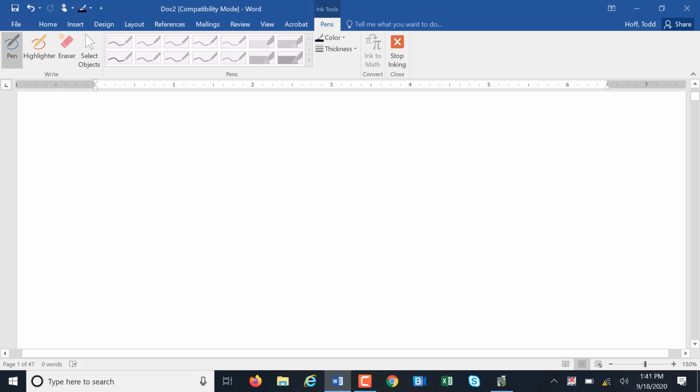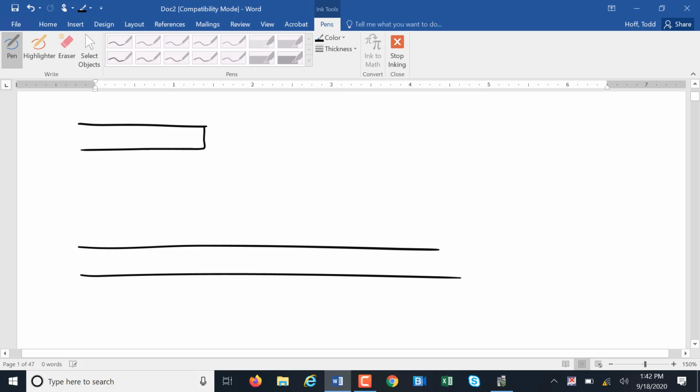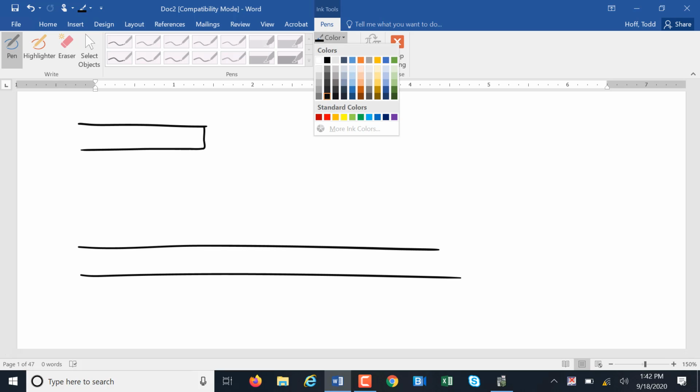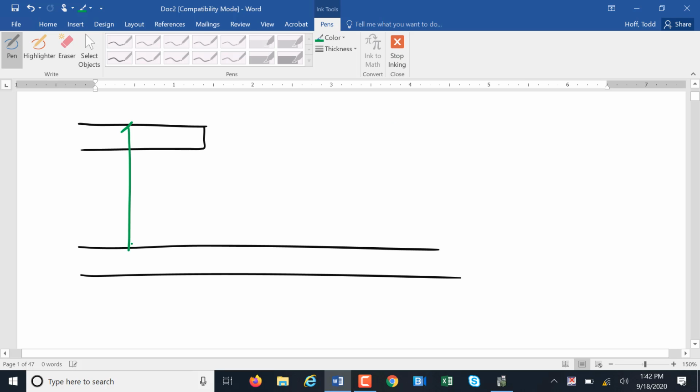Okay, so there are some other construction-related concepts with the math we've already done that I want to make sure you guys understand. Let's talk a little bit about stairways. So we have story to story height. It's usually called just story height. It is the distance from the top of one floor surface to the top of the next floor surface. Obviously, stairways go from one to the other.